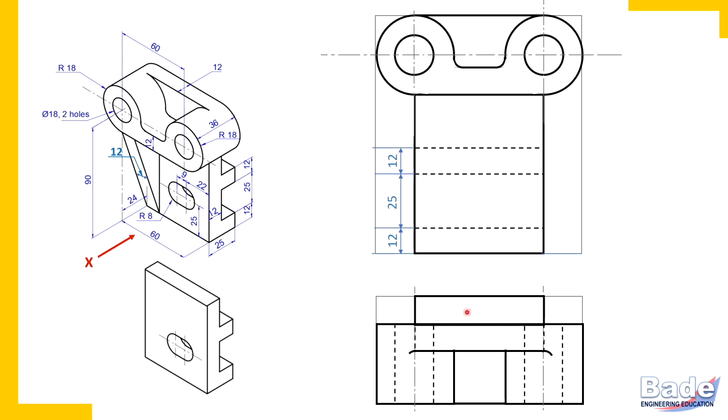Now in the top view, same three edges. So these edges we are drawing here in the top view will overlap with already drawn edges, and that is why these three edges or the edges from these corners will not appear in the top view. Not appear in the sense they are already overlapped in the earlier drawn edges.